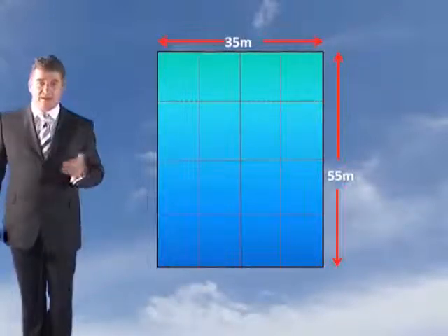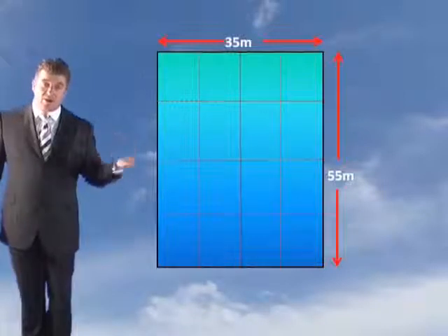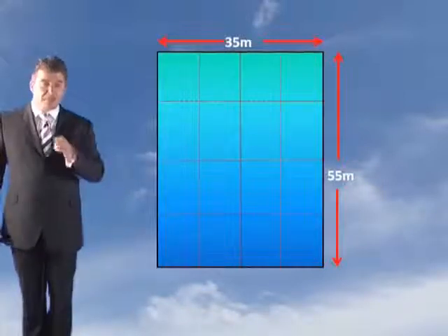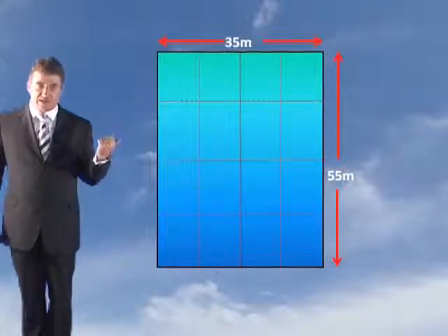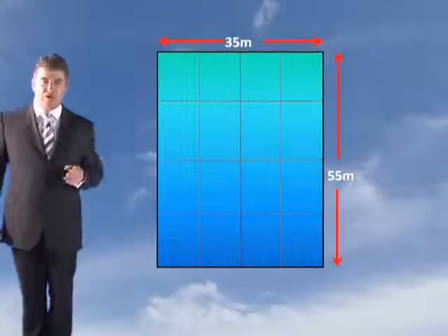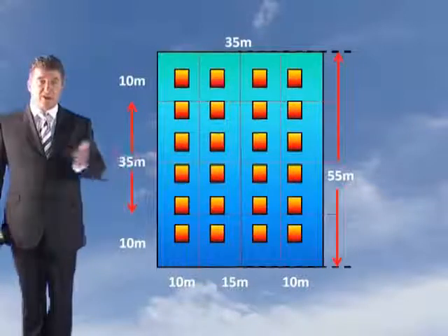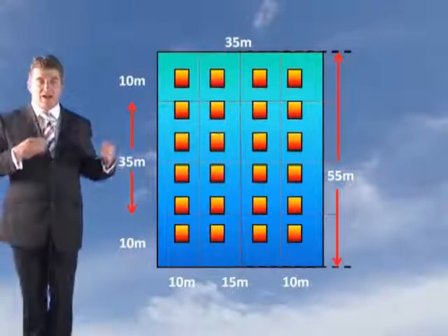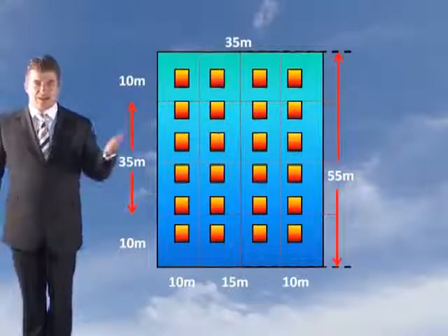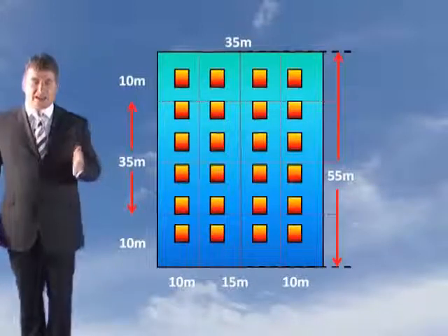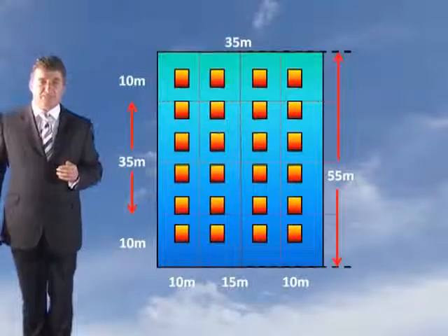That's what we'd need. Now in this case, we know we need 24 anyway. So do you understand? In a way, we need more than what the stagnation rule says. So now we've got to have 24 ventilators somewhere on here. And this is how you do it here. You just spread them out, axisymmetric, all the way around the building, spread it out in the reservoir. So this is what you'd need, 24, and it satisfies the stagnation check as well.